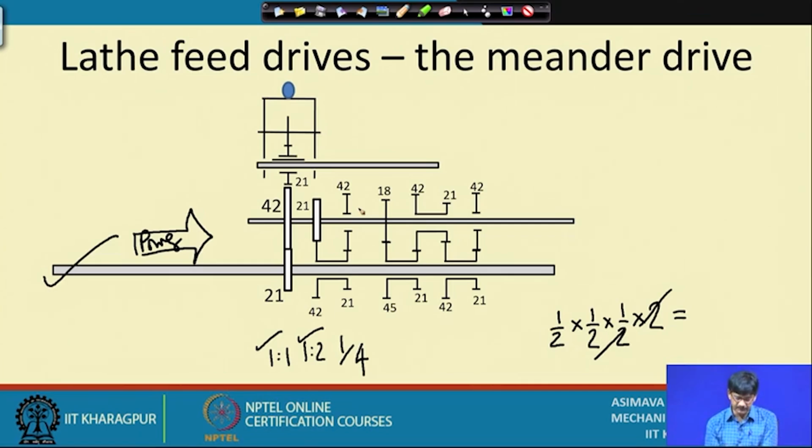In addition, if we extend it to get those ratios of 5 is to 1, 10 is to 1, etc., we can employ these 2 gears. How come this center distance is accommodating 2 different gears? Because the sum of the teeth, you will find that it must be the same. Okay, 42 plus 21 is 63, and 18 plus 45 will also be 63.